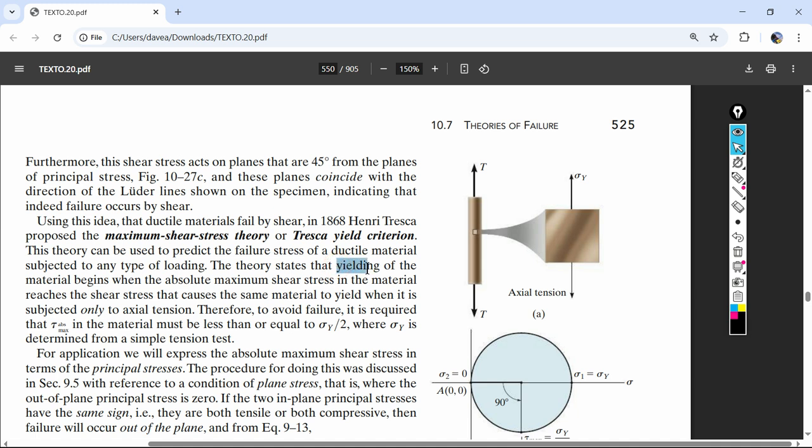We have to say failure is yielding, where it's just the presence of getting nonlinear. The second that happens, we've called it for that material, even though, like I said, it can yield 30% and still maintain its strength, but it's just past that linear zone. Most things aren't designed past that linear zone.